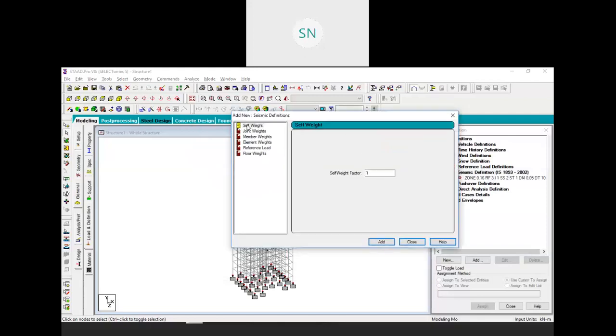Now the loads, first self weight, then in the dead load we are considering a 9-inch wall, or let's consider a partition wall, right? So 4.5-inch wall, we have 6.5 kilonewton per meter wall load. This is my wall load.